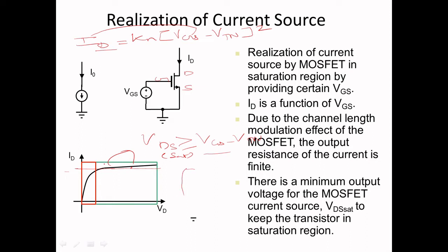You can see here in the MOSFET, in this place the current is almost constant. The change of ID with respect to VD is very little. This is the part we expect. We know that a normal current source is something like this, right? So we can see a constant current here, and also a constant current there, almost the same function. That means I want to make a MOSFET work in the saturation region, so that I can bring the functionality of a constant current source by using active elements.